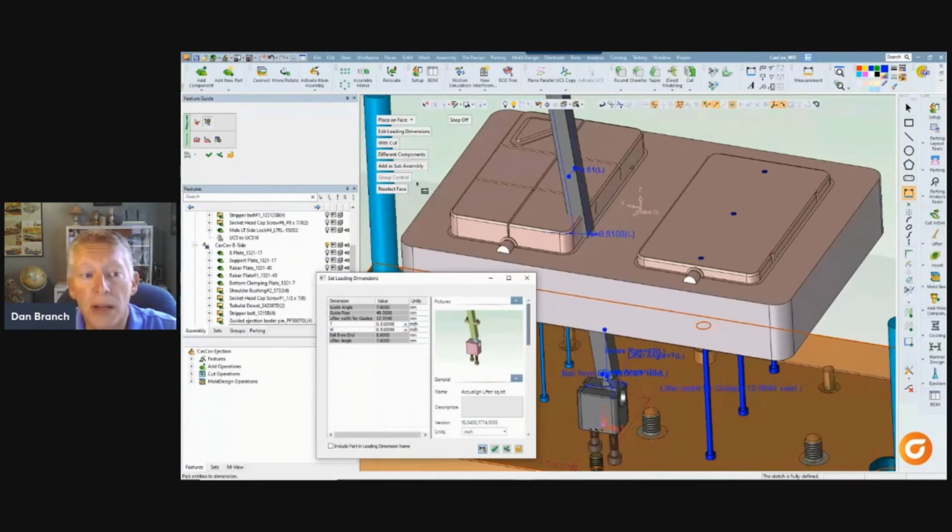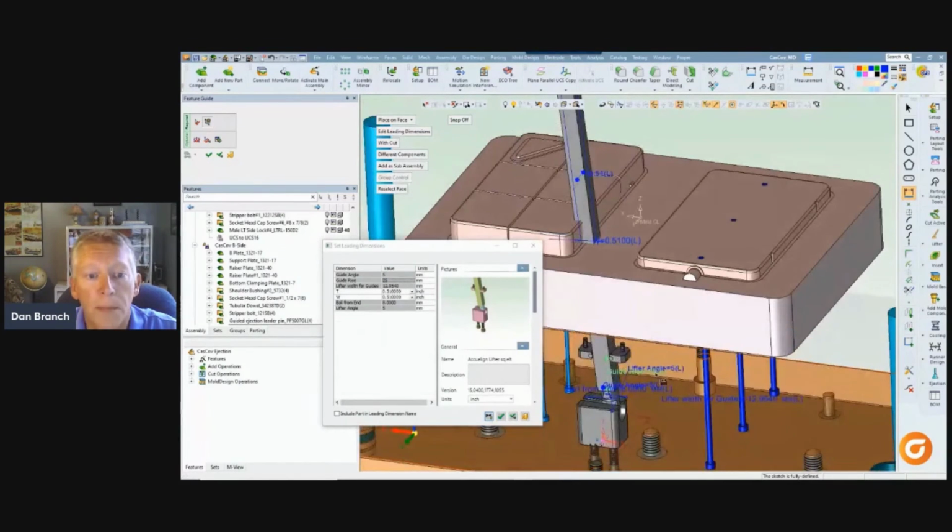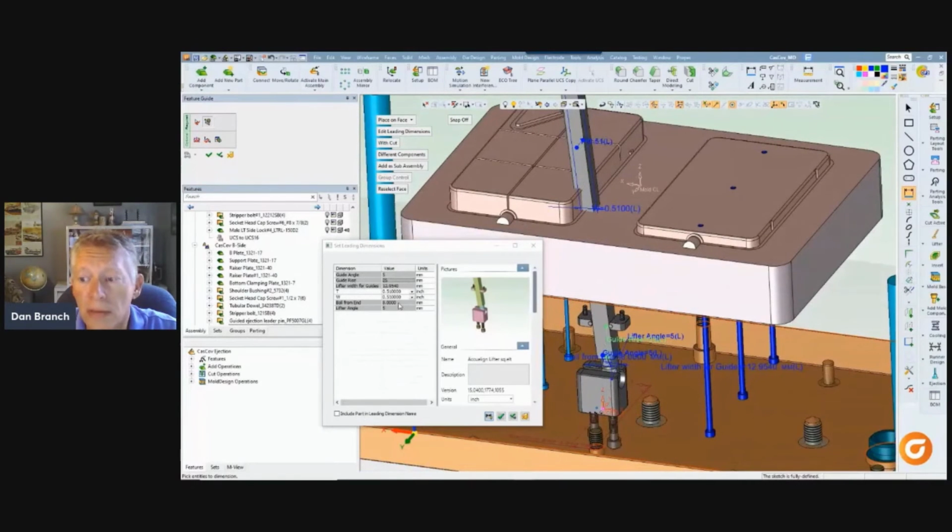For example, the lifter angle. That's related to the depth of the feature being molded, of course, but I know I can get by with just 5 degrees in this case. Also, the height of those lifter bar guides. Those guides are really a nice feature of these Aculine lifters. So that's a dimension to adjust, or you could even make a smart relation to the plates for it. Even where that lifter ball sits in relation to the shoe is an adjustable dimension here.